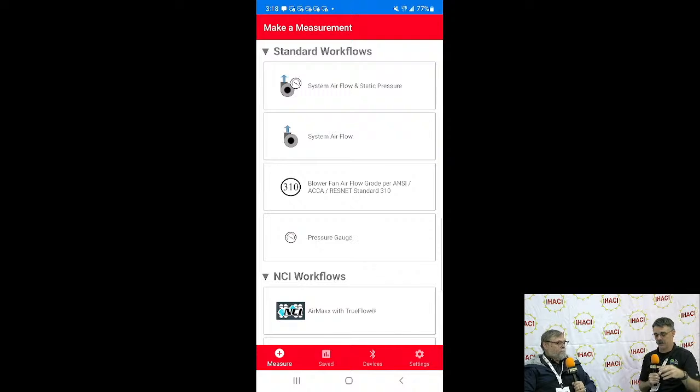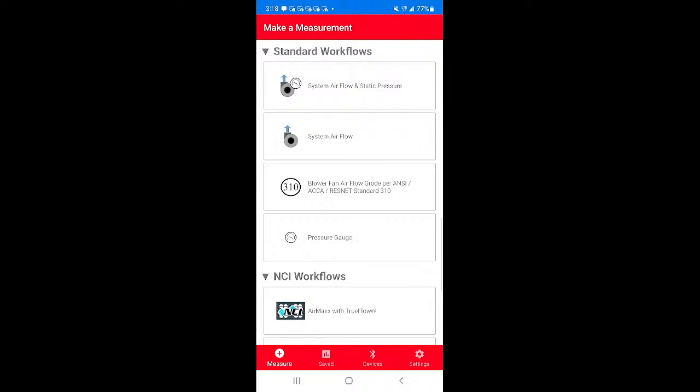Yep. Because Steve Rogers over at the Energy Conservatory, they recently did some testing, and I believe they found that around a 0.7 external static pressure, if we get higher than a 0.7, it's going to start costing that customer more money than what it would cost to run a PSC motor. Right. So yeah, maybe that ECM is going to push harder, but it's going to cost that customer more money. A lot more money. And it's going to significantly reduce the life of that EC motor.